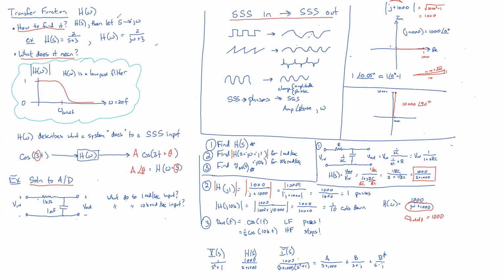No. All you do is you change S to j omega. I'm not sure if that answers your question. There's two ways to measure frequency, either in hertz or in omega. And we're going to work out everything in omega because it makes the math easy. And then the very last step, if you need a frequency, we'll convert it to frequency. So we analyze this in terms of omega.